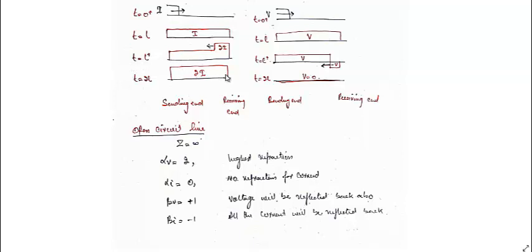When the current goes back to the sending end, it has reached 2i, and if we keep on seeing the reflections, it will reflect back with a positive current, it will be 3i, and then this will happen. You will see that the total current will build up depending upon the voltage and the impedance of the line, and the total voltage will swing back and forth, and the total voltage at the receiving end will ultimately be equal to 0.